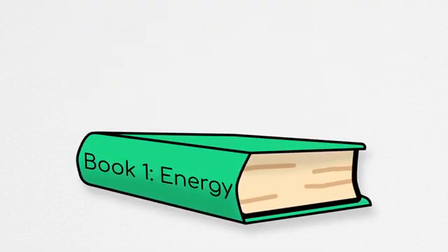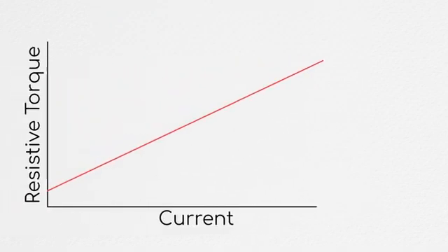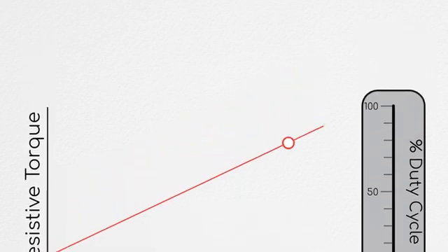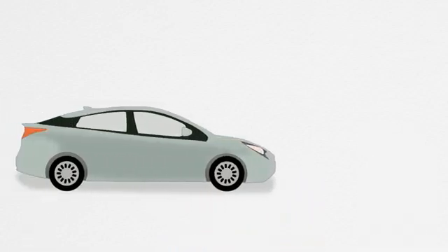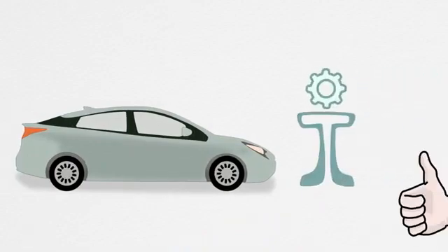However, with regeneration, electrical energy is really only half the story. The other important side that needs to be considered is the mechanical system, because, as we said earlier, the torque produced in the motor is approximately linear with the current running through the motor's coils. And by modifying your PWM period, you modify this current, varying the braking torque produced. So, if you're just maximizing the energy you're reclaiming, you may be producing non-optimal torques within your motor. But when a driver presses the brake pedal in their car, more often than not, producing the right braking torque is more important than optimizing the energy reclaimed.